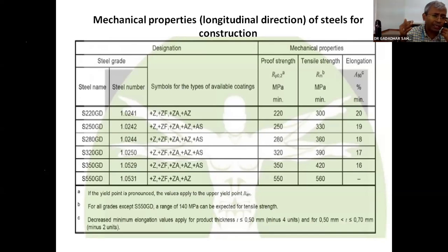It could be possible that our tension leveler may not be sufficient to achieve that much flatness, because as the material gets thicker, though the YS and UTS will remain the same, the cross-sectional area is larger, so the total required load will be higher. I don't know if it is feasible, but we may explore.